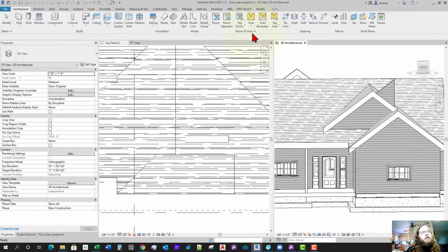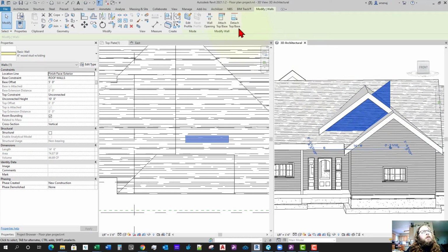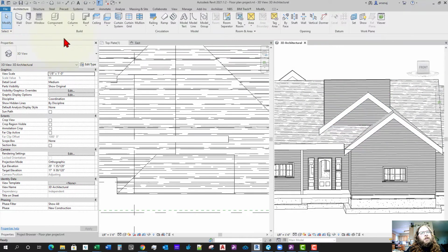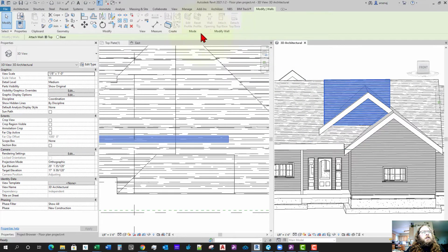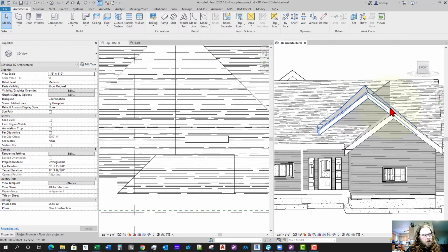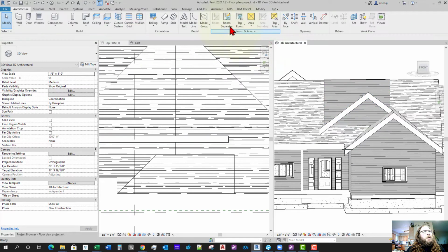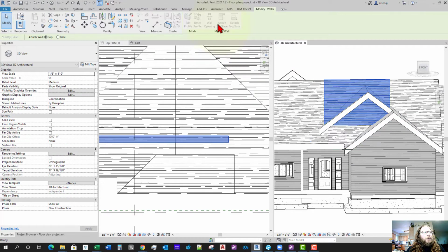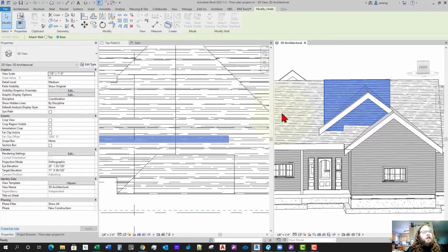attaching. Oops. So I think what we'll need to do is click the wall, detach all, select the wall again, and attach. Let's try to attach the top without the base being attached. Nope, see, it just does not want to let us do that. So I hit undo, grab the wall. I'm going to attach the base. Oops. I'll select the wall, attach top, base, pick base, pick this roof, attach again to the base.